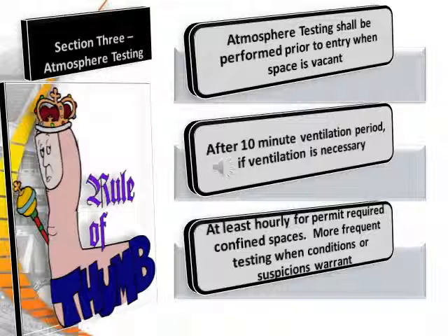Atmospheric testing shall be performed prior to entry when the space is vacant, after a 10-minute ventilation period if ventilation is necessary, and at least hourly for permit-required confined spaces. Perform more frequent testing when conditions or suspicions warrant.